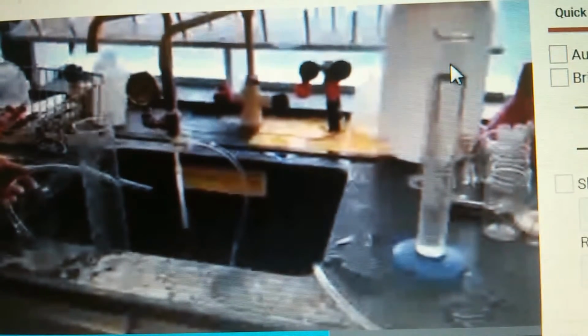For the second experiment, you're going to be measuring the flow rate of the suction, which means you're going to have to measure 4 things in this experiment. The first one is the amount of water that comes through the aspirator from suction. You're going to have a graduated cylinder filled with water, and you're going to mark the place where the water level reaches in the beginning and then at the end, so you know how much water flowed through the aspirator from a hose that you're going to dip into the graduated cylinder below the water level.